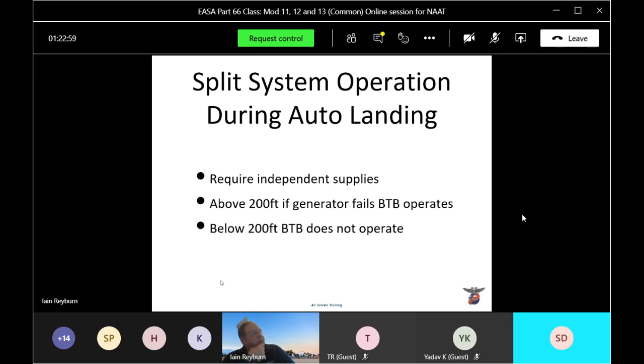Okay, gentlemen, we'll make a start. So now we're looking at this thing called Autoland. We said, hopefully before the break, that like stall warning and autopilot, one of the regulations is that it has to have an independent power supply. So whatever Autoland system is supplying the pilot, let's call that the non-essential generator. The co-pilot will be the essential loads, the essential generator.